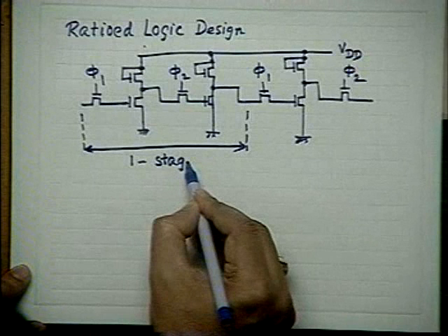You see that here there is nothing but what are called inverters with steering gates. These are all simple single channel NMOS inverters. But at the input of each inverter, I have a MOS switch.